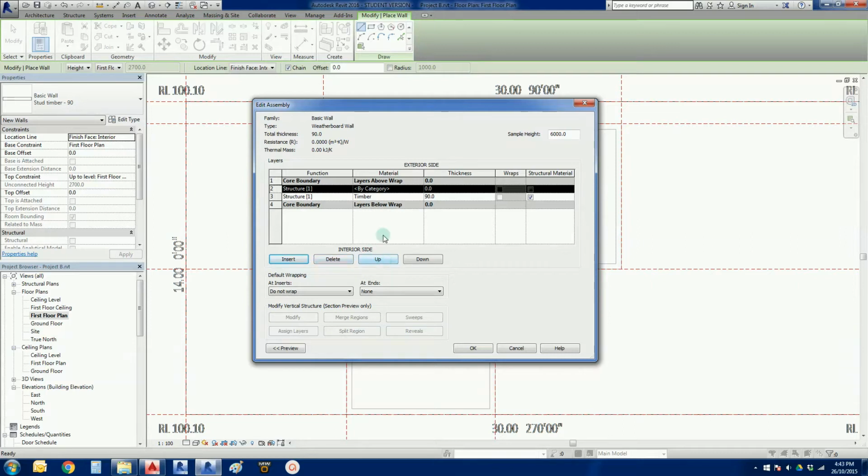So I'm going to locate that up, because here's my exterior side. I want this layer, there we go, click up. I want this layer to be outside of the core, because all it is, it's a veneer, non-structural element, and I don't want it to be part of load-bearing element performance or behavior. So now I can go in here and I can change some of these bits.